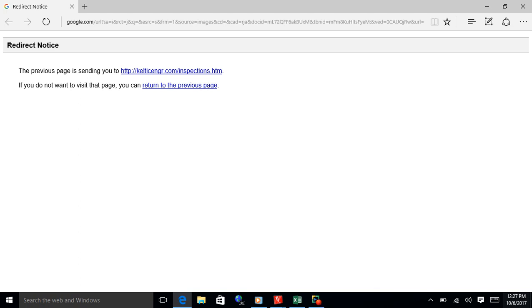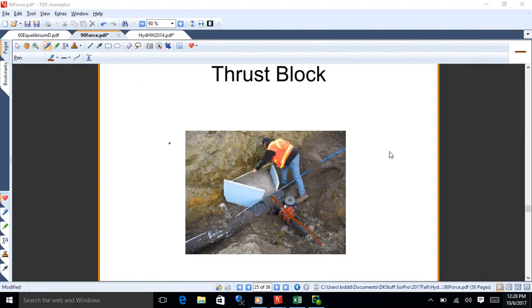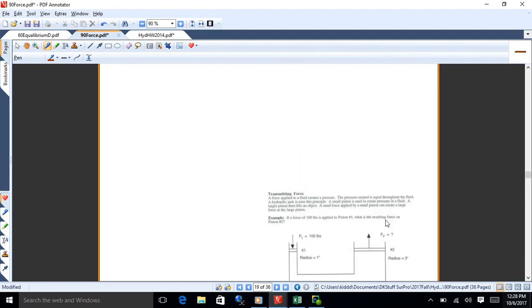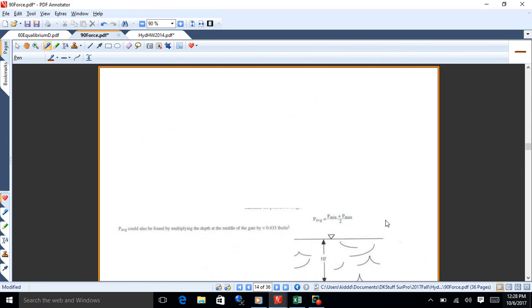Oh, okay, I see. So we have an unbalanced pressure pushing that way. And if you just let it sit there, eventually that pressure might cause some leaks and things, okay? So you put that concrete block there to absorb that force that's being exerted by the water pressure on that back pipe. Okay? So those are just some examples of some of the forces we run into.